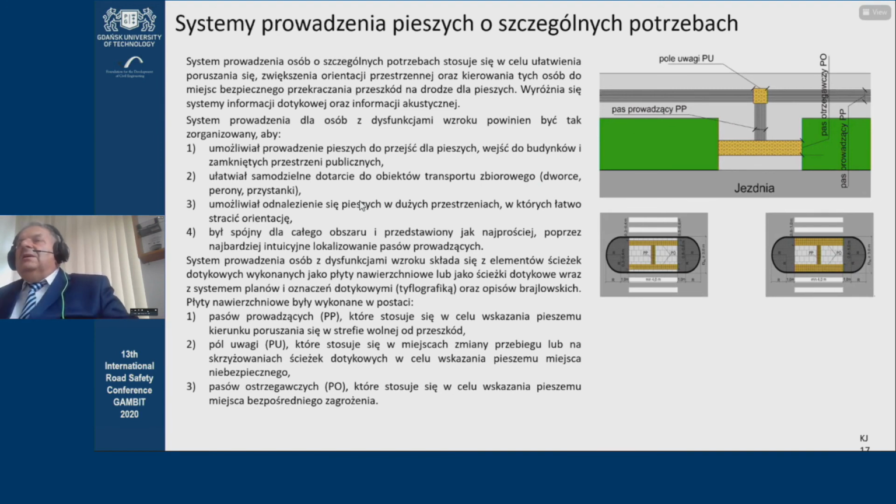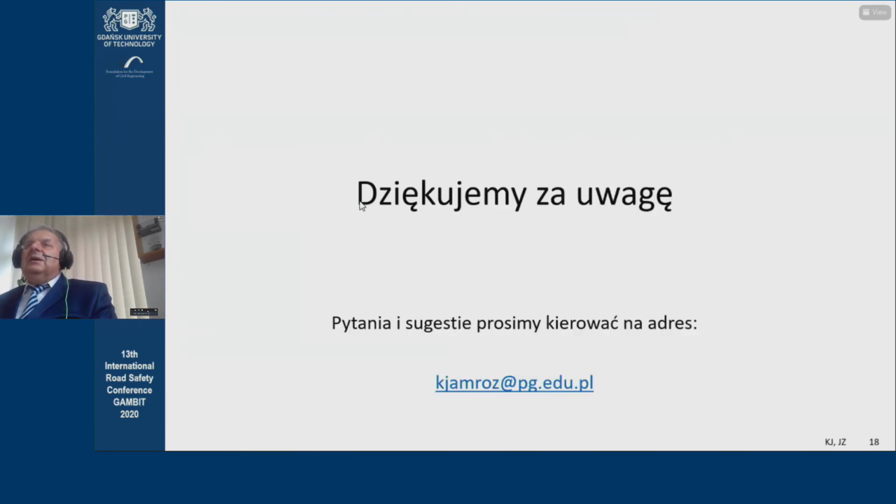What we need is to have clear contrast. The contrast between the yellow belt and then there is this yellow surface of the paving blocks. The contrast must be over 30. If there isn't enough contrast, it won't work. There's still an ongoing discussion about that. It will continue in October. Whether we're going to move it closer, that lead belt closer to the curb, the warning belt, or move it away. That was all, and thank you for your attention.